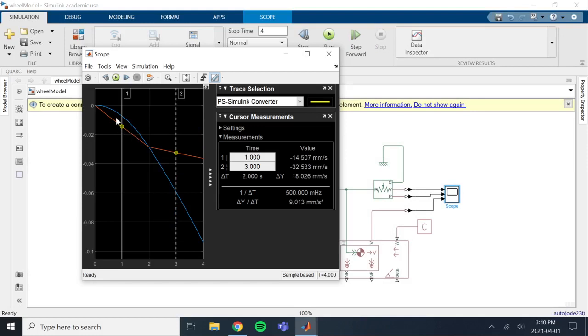So now this looks really different. You can see before the torque is even applied, the rover is moving backwards. So the headwind is pushing the rover backwards. And then when the torque is applied, it's trying to oppose the headwind, but it's still not enough to get it to move in the forward direction. So the speed here in red did start to decrease slower. So you know that the wheel is trying to accelerate. It's just not enough to overcome the acceleration of the wind yet.